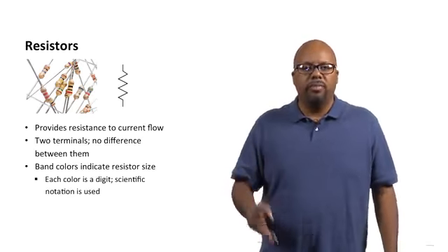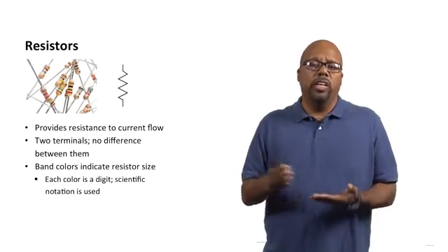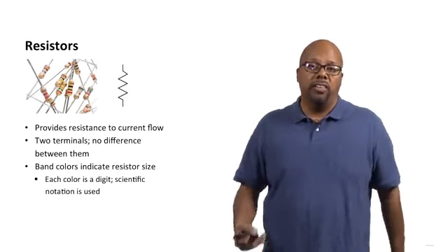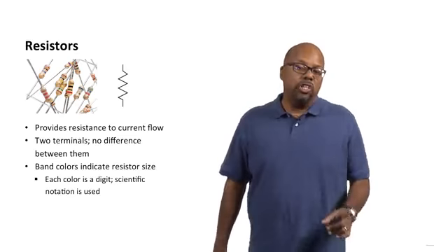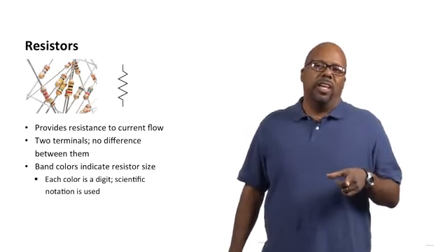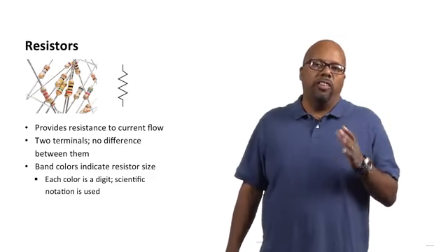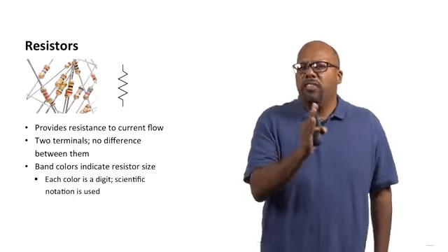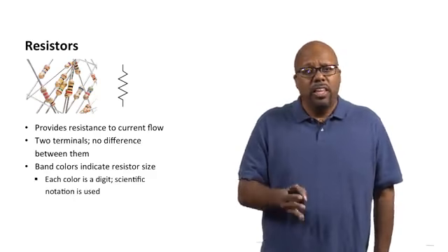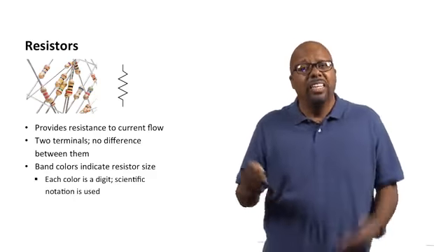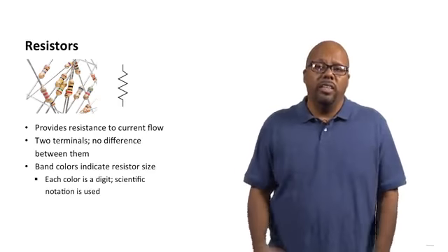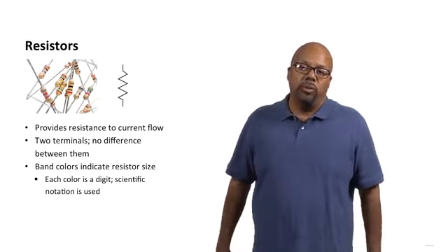It's sort of a tedious thing. And you can read the colors off the bands and figure out the size of your resistor. It's tedious also because of the coloring. How good is your estimation of coloring? Meaning they'll have shades of colors that look kind of similar, like the orange sometimes looks like the red. It is awkward to read these bands, but that's what you have to do.